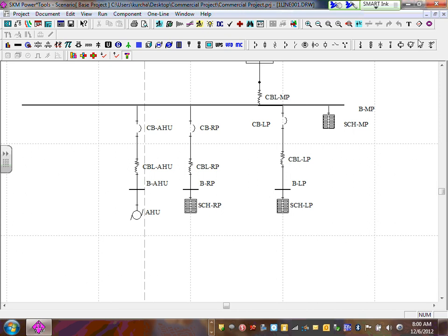Do we have to change the conduit or anything like that? Remember that I copied, good point. Remember, I copied this one, guys. So when you copied this cable, that cable was EMT conduit, right? So I don't have to worry about that one. All I have to worry about is just sizing the cable. Remember how cloning becomes really cool? It saves you time going sizing, finding the right size, right type of conductors.